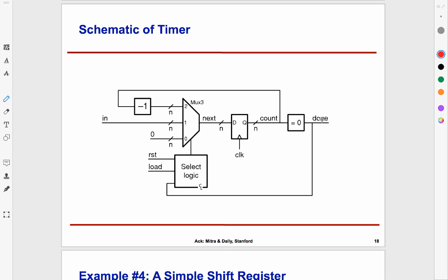So again, once I have that program-like description of the Datapath, coming up with this is playing with multiplexers and some operations. What you see out here is the same pattern we saw in the previous examples. There is stuff happening out here on n bits, and then stuff happening out here which are 1-bit controls, or very few bits usually.